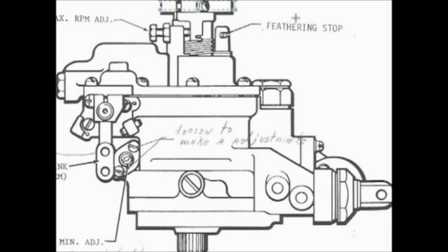The shortcut is that you push your power lever or propeller lever, condition lever, wherever you want it, and so it's hitting the stop, and then you just slip it right onto the shaft. It'll save you a little bit of time.